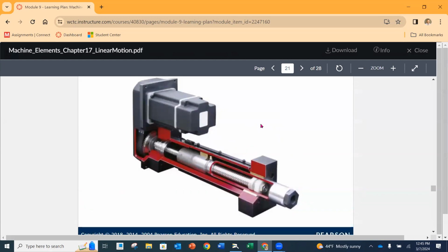Yeah, there is a lot of different linear motion, right? You can use cylinders. Yeah, so cylinders versus a screw. With a screw, you can actually position it and you can keep track of that position as well. So if you want to move a quarter of an inch or an eighth of an inch or 1/1000, you can do that with a ball screw. With a hydraulic cylinder, it's more or less going to go through it and stop, go back. Right. That positioning accuracy as well.